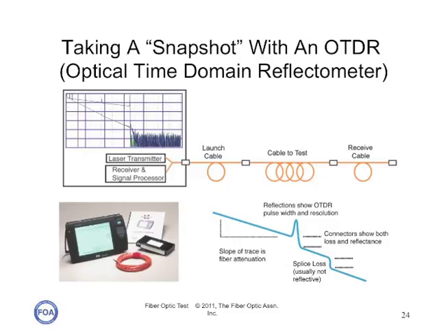We can also take a snapshot of our fiber optic cable plant with an instrument called an OTDR. It works sort of like radar, sending a signal out the fiber and creating a picture of the loss in the fiber and where events like splices and connectors are. OTDRs are expensive and a bit hard to use, but they're highly valuable tools to diagnose problems in the cable plant. We also often, on long distance lines, take that snapshot and save it in case we ever need it in the future to diagnose problems or to restore the cable plant.